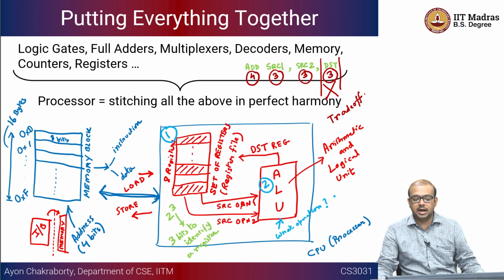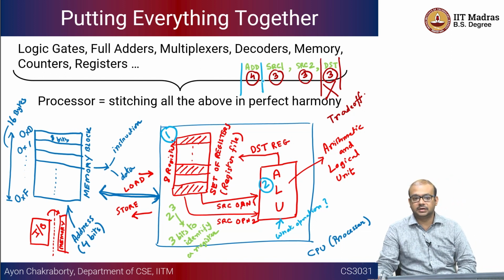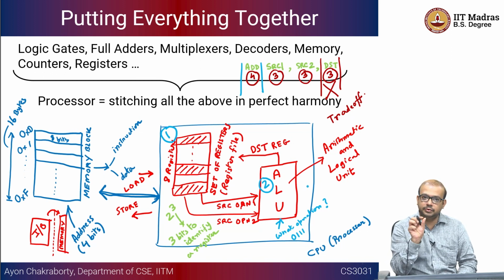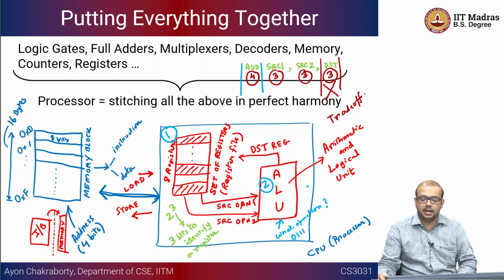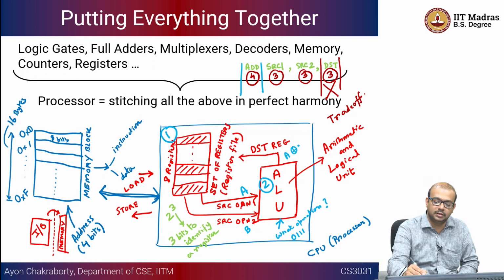It has to be told, and these 4 bits of the instruction are going to contain that information. Whenever it sees, let us say, 0101, which is 5, it understands it is an add operation. So, the ALU is not going to choose an XOR or a NOT, it is going to choose the full adder. Whenever it sees, let us say, 0111, which is 7, maybe the 7 stands for an XOR operation. Whenever I see 0111 here, inside the ALU it is going to choose the XOR operation, and if you have A and B coming in, it is going to automatically compute A XOR B.